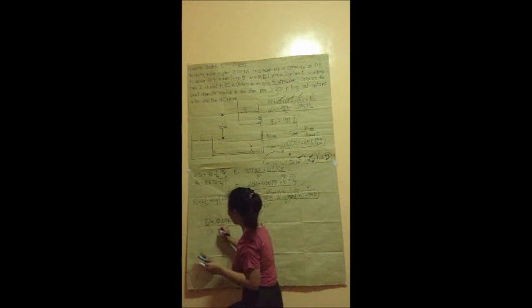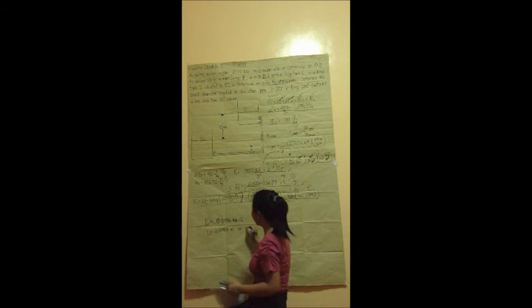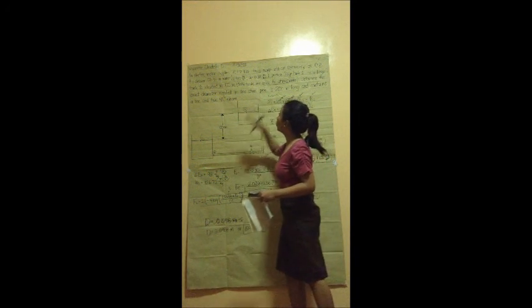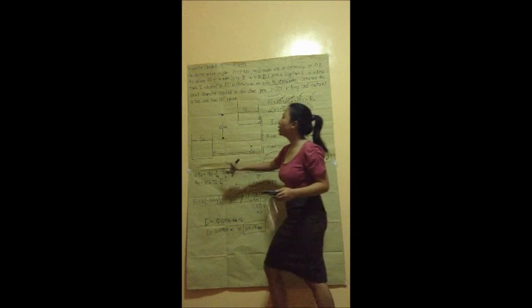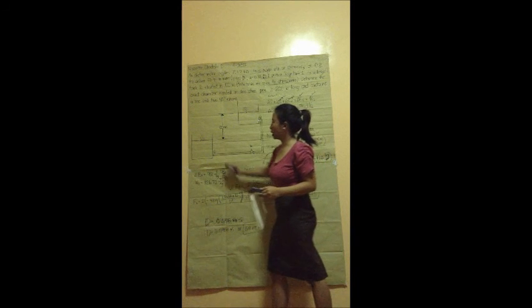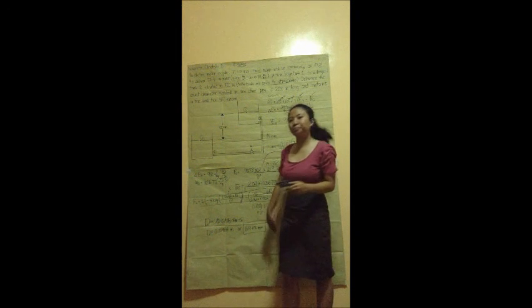The final answer is 0.15968 meter, or to give this a more appealing appearance, we can say that the answer is 159.68 millimeters. So, the size of the diameter needed to deliver the 50 liters per second of water from tank 1 to tank 2 is 159.68 millimeter. So the diameter here in the pipe that will deliver is, thank you.